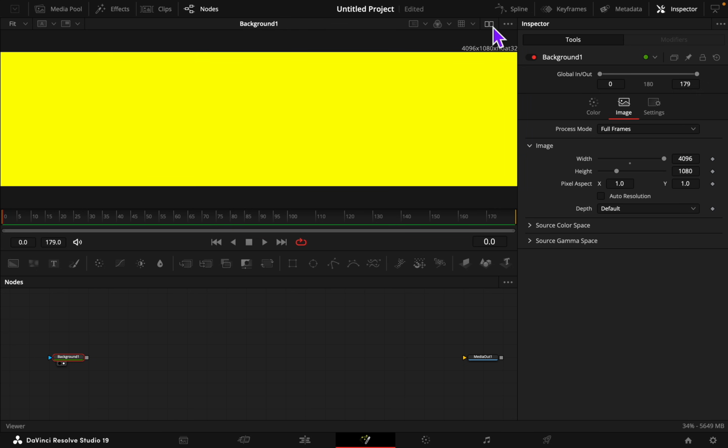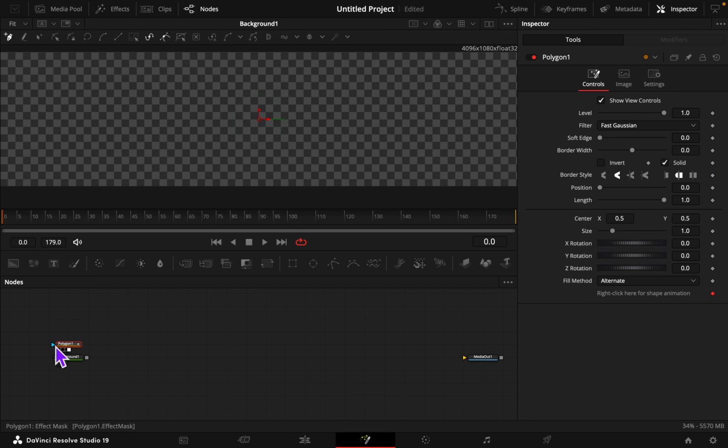Now we will introduce a polygon node. Position 2 points on the viewer. Select the points and publish it. Right click on this and remove the polygon polyline. Set the point 0 x value to 0, y value to 0.5, point 1 x value to 0.8, y value to 0.5. Set the border width to 0.004.